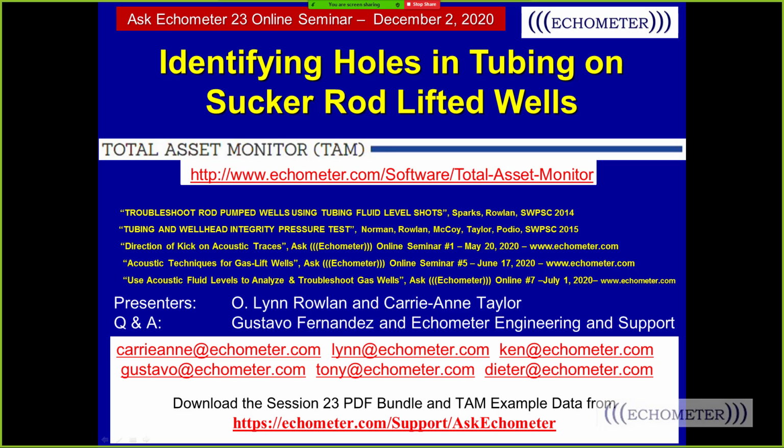Yeah, the paraffin is hard to detect because it plugs up the tubing. You can't really see past it, so I'm not sure you can detect the paraffin. Scale, you have to have a discontinuity in the wellbore to see an echo. And if scale is gradual or corrosion is gradual, you just don't see a sudden change.